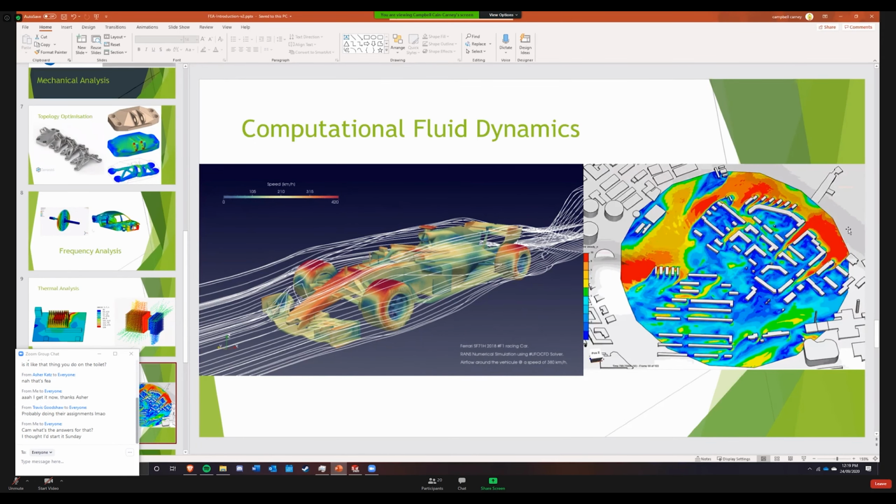That's everyone's favorite thing, but you can also use CFD, as I said before, in cityscapes. Like I was saying, you've got these Venturi effects down between the buildings here, so you can imagine that these airspeeds are quite high, and that's something that you try and avoid when you're designing a CBD. So Civil can use it for things like this as well.